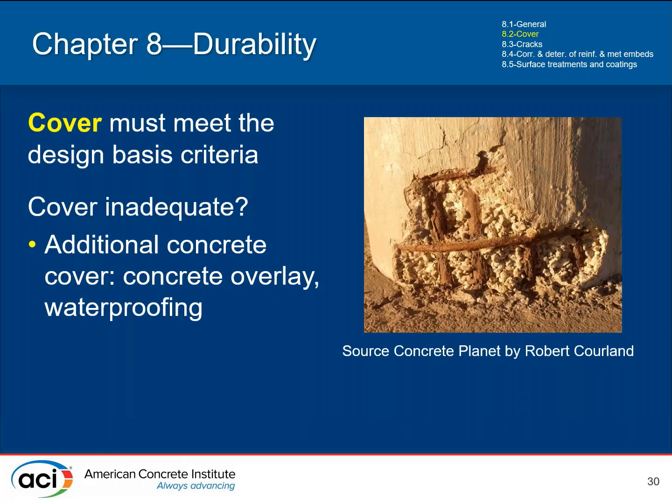And when it comes down to it, the understanding or the ideal behind durability and what the requirements are is that you really must meet the design basis cover. That's kind of the objective here, and that's stated in the code. Hey, we're trying to get the design basis cover. So whatever was the cover that was required by the code that it was constructed under, ideally, that's what you should be getting. Unfortunately, that's not always realistic. Once it's been built, let's say, as you can see in the picture on the right here, it was built and it didn't comply with the design basis cover.